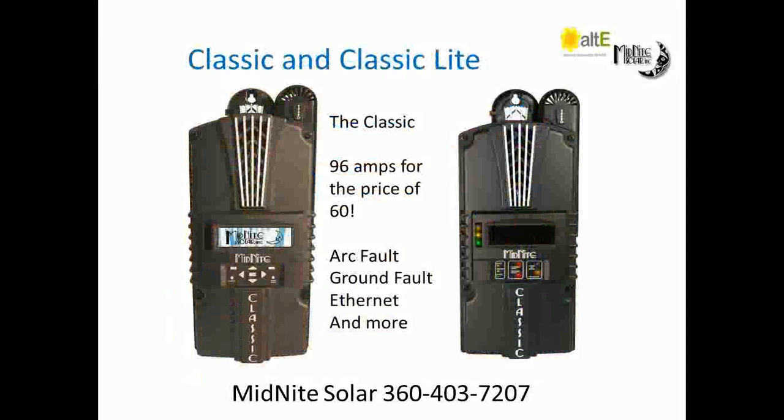Some of the other features are MPPT for wind, much more programmability for micro hydro, fuel cells, different battery chemistries. We have logic inputs so that if you're using a battery management system, we can stop charging when the management system tells us to, instead of having to have the old clunky relay that disconnects you. We actually take a logic signal from them and just stop charging when they tell us to. Just a lot of unique features. I mean, it is definitely the most sophisticated, powerful controller out there. It's been 7 years in the making, and for reference, Bobby did the MX60 in less than a year.